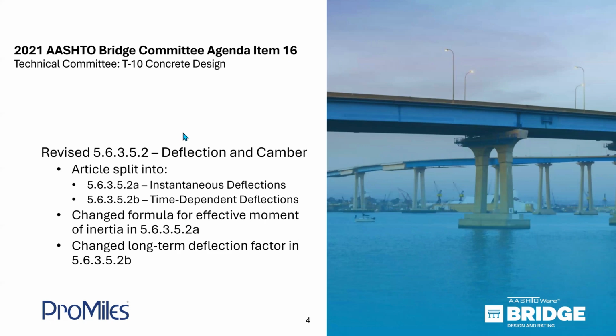So the biggest change introduced by LRFD 10th edition for concrete deflections is that the article that covers those has been split into two parts, A and B. The first part is on instantaneous deflection. The second part is on time-dependent deflections. There's also a name change. They used to be called long-term. Now they're called time-dependent. And in both of these changes, the formulas have changed.